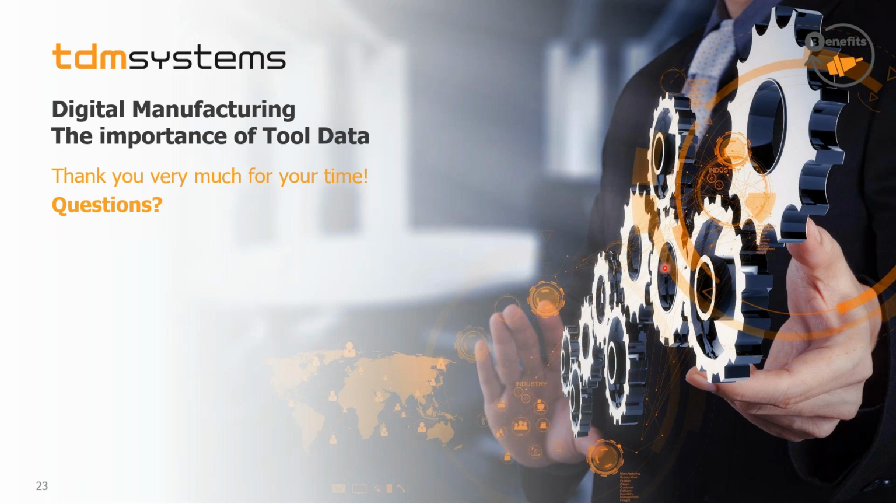Second option is, of course, if you have a live connection with the machine tool, you can also monitor tool life and define actions on tool life. So if tool life drops below a certain warning limit, you can request a new tool for the machine. So it's two different things. We manage the tool life as a theoretical value. You can add historical data manually, and we can manage live tool life. Live tool life. That's a silly word.